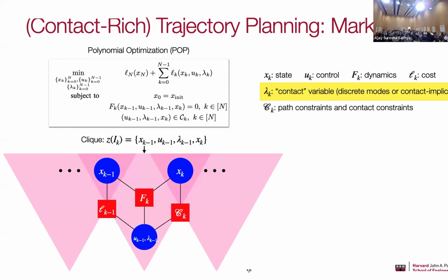So if you do some simple math, if you do trajectory planning with horizon equal to 50, and maybe the dimension of the states and controls are maybe 20-ish, then you get a polynomial optimization problem with about 1,000 variables, right? So therefore, based on the simple math I did, you're going to get a trillion-variable SDP, if you don't exploit any additional structure.